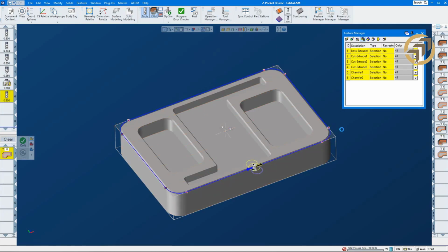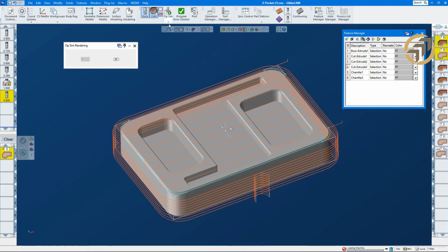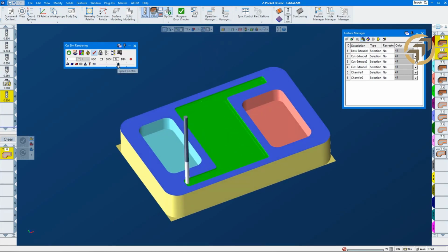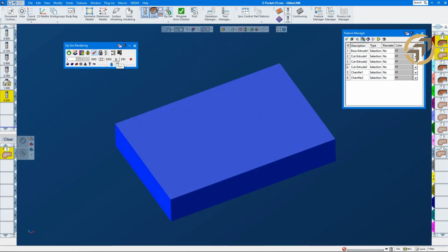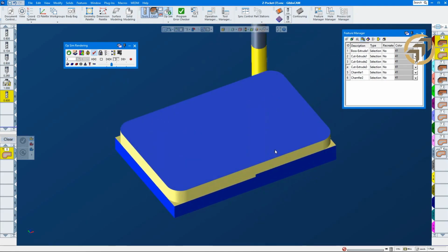And so basically it goes out and creates a toolpath across the top, and it creates a contour down the side. So very, very easily done, and it's quick. And this is kind of nice. Now again, it's a little bit out of order, so I would take this up here and move it around. And then we can look at our op sim. That went kind of fast, so let's rewind that really quick. There's our face. There's our cut around the outside.